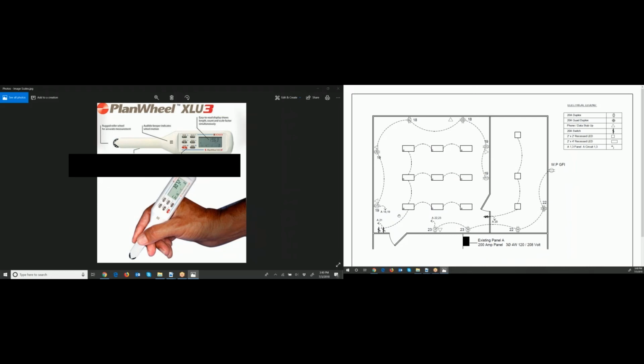Here's how to roll this off. What I do is I usually over-roll to allow for the height. Say I know the distance is 12 feet, the ceiling height is 12 feet, the switches are about 4 feet, so I just roll the scale X across the drawings till I know it's about 10 feet, and then I roll over and up, say, to the first light fixture. And then I roll slightly beyond it, called over roll, to make up for the amount that goes down into the top of the light fixture.